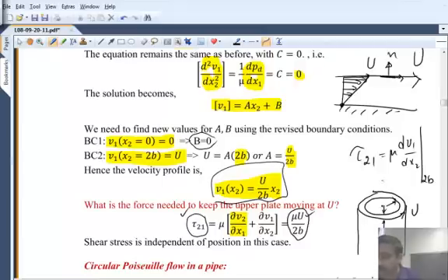And the inner one is suspended on a torsion bar. A torsion bar is basically a steel wire or something that will deflect, but it will not spin. By looking at the deflection of the inner cylinder, you can find out the torsion, the torque. Torque is force times the distance. You know the distance, so you can calculate the force, so you can figure out what the left-hand side is. You control the right-hand side, the velocity, through the motor speed, and you can measure through the torsion bar the torque applied on the inner cylinder. And so you can back-calculate the viscosity.